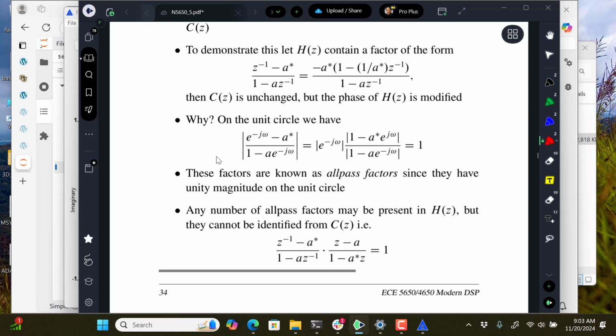Normally you'd think in line of sight communications, like the Cheyenne Mountain down there, if I was getting a radio signal, the line of sight to me would be the shortest path. The longer path would be one that would go to some peak, maybe Blodgett Peak or one of those that's further north, and then it would reflect and come down to me.